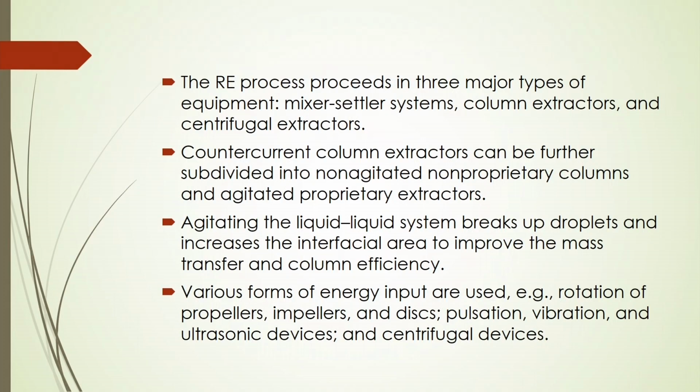Various forms of energy input may be imposed for the formation of interfacial area, like rotation of propellers and impellers, pulsation mechanisms, and vibration. Even ultrasonic devices and centrifugal devices may be used for the creation of interfacial area for better mass transport.